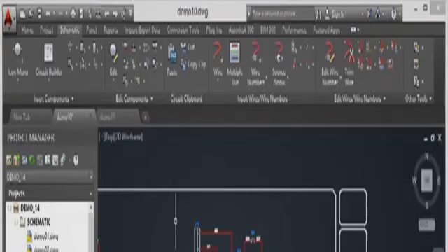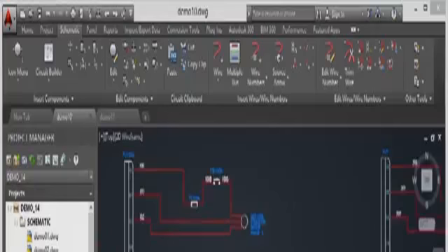In the previous video, we looked at moving a circuit in our AutoCAD Electrical drawing. Now you can copy a circuit in a very similar way as you would move a circuit. We're staying in the Demo 14 project, we're still in the Demo 10 drawing, and I've moved over to this circuit here that starts with the wire numbers 100, 101 and 102.